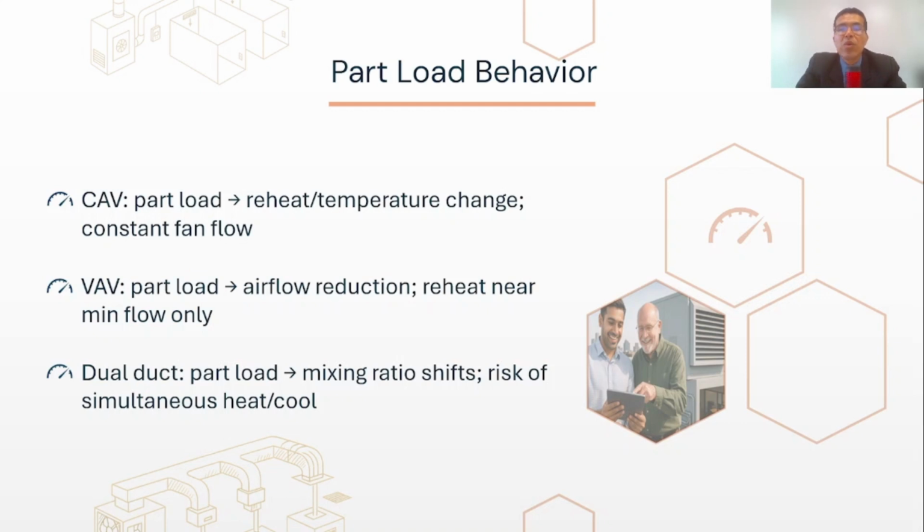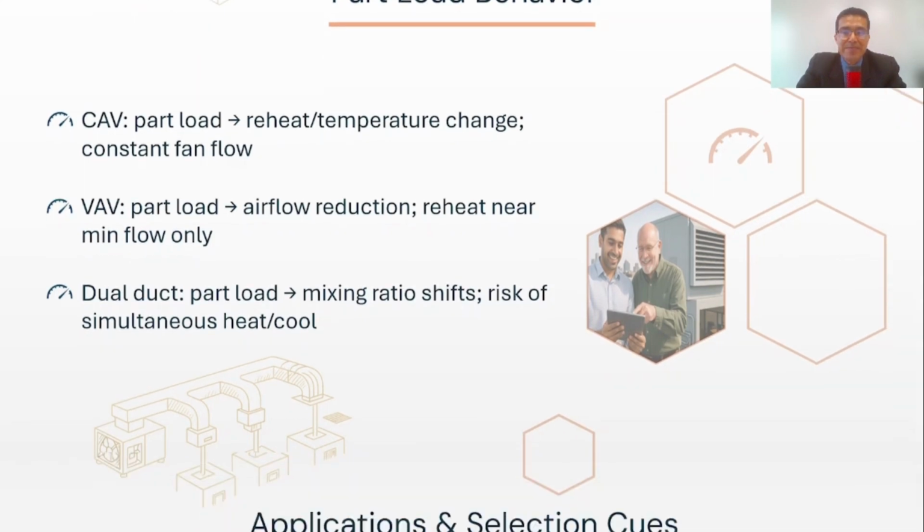While this provides very fast and precise temperature control, it carries the risk of a mixing penalty, which is the energy waste that occurs when the heated and cool air streams are combined, effectively cancelling each other out.